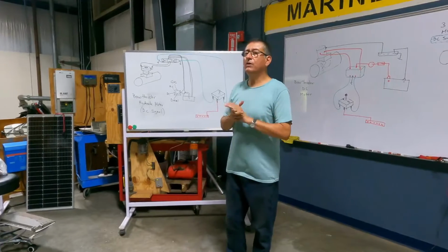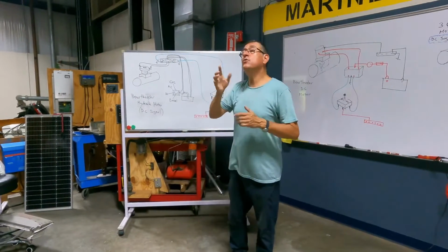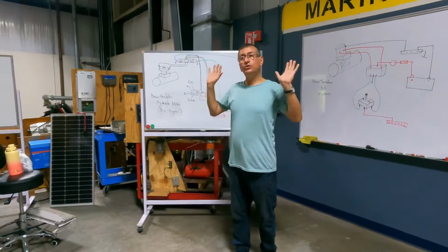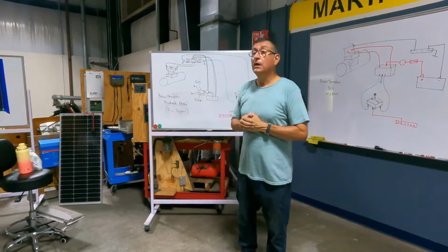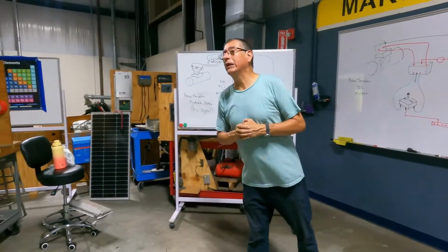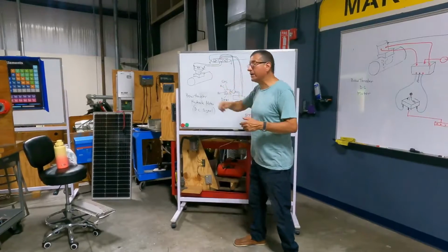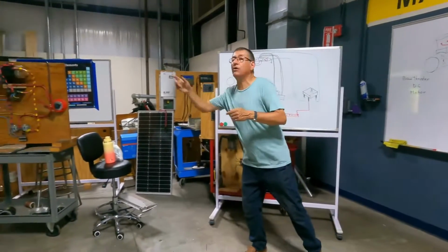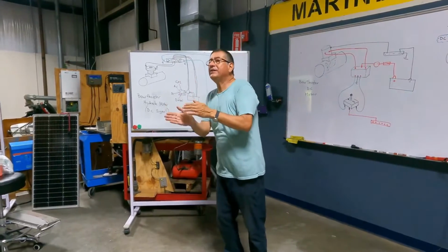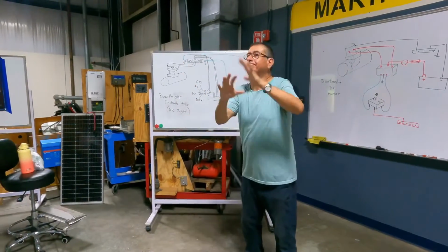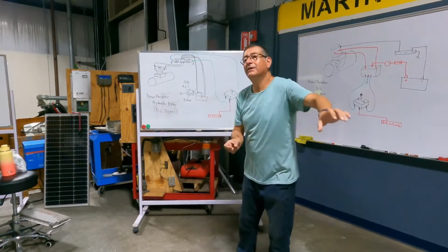Air. Okay, what is, in that case, the next step? If you have air in the line, suddenly, it's because what? You have a leak somewhere. Because you have a leak of oil. You need to follow the lines with your fingers. Follow the lines. Oh, it's too much distance. Follow the lines. Oh, in this section between the salon and this, I don't have access to the line. The line is passing through the pipe.